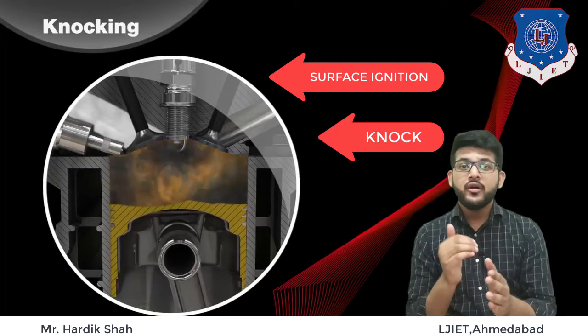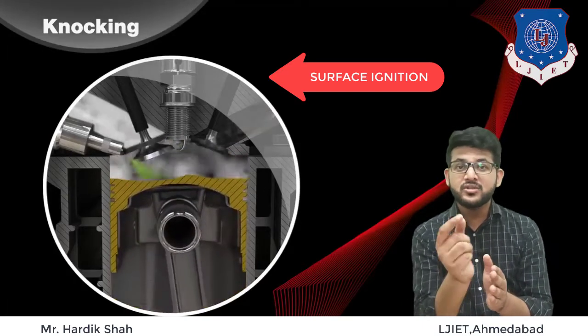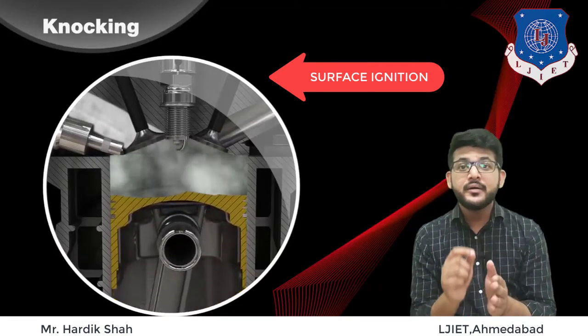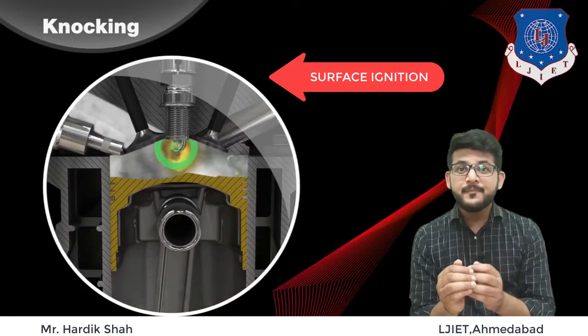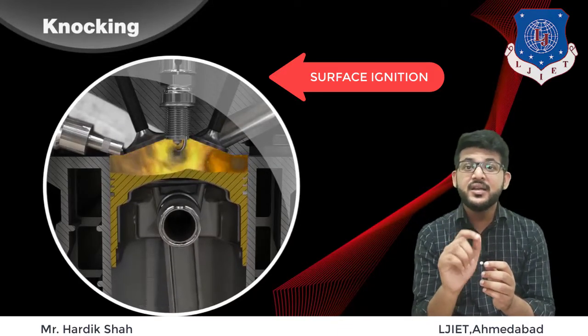So what is surface ignition? The combustion originates from some hot spot in the combustion chamber. The flame front generated by the surface ignition is similar to the turbulent flame generated by the spark plug, but in this case the moment of ignition is not controlled. The pre-ignition is most dangerous because it advances the ignition moment.